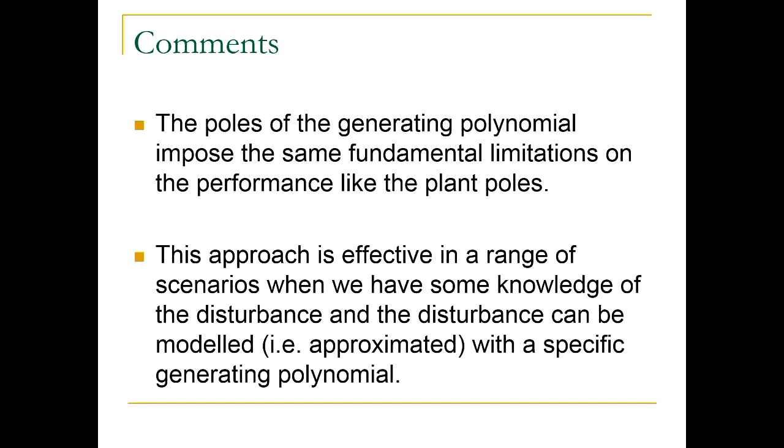In terms of overshoot, rise time, and things like that, you may have extra limitations. You are achieving zero steady state error, but you might not be able to achieve some things with your overshoot, rise time, etc. Sometimes you may need to give up on zero steady state error, because overshoot or rise time is more important.